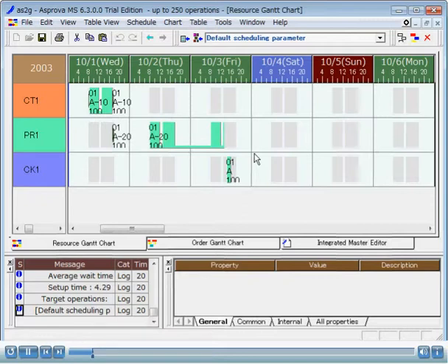They have also changed the inspection method for the sake of quality improvement, which requires them to make necessary adjustments, specifying according to resource quantity as a resource quantity constraint for a resource. First, let's try to be able to handle the increase in orders. Since visual management has been realized and we can now identify that process PR is a bottleneck resource, let's add a new resource to that process.